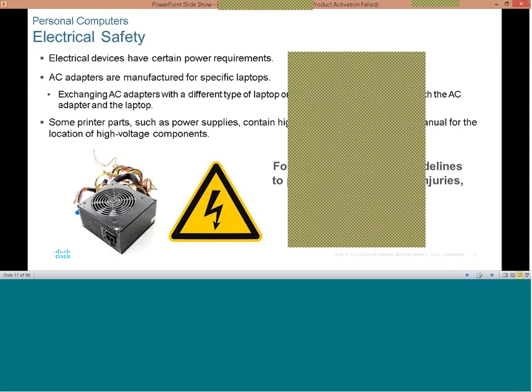So the cost of getting a fuse might be very small, not too expensive, so you can actually repair the power pack. But like I said, make sure you get the right component with the right specification, so that you don't change the default setting. That might damage the system.